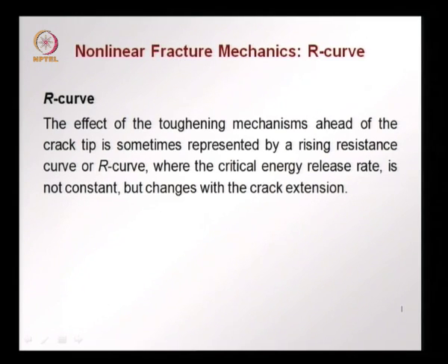How do we model these mechanisms? We understand that since there is a zone where energy is dissipated in front of the crack, we cannot apply linear elastic fracture mechanics directly. So, there are different models, the simplest of which is called the R curve model as part of nonlinear fracture mechanics.